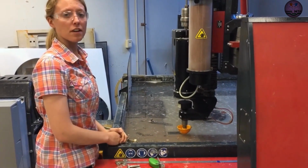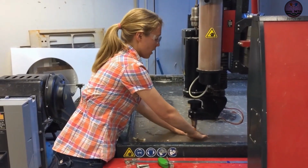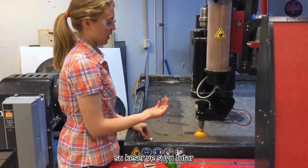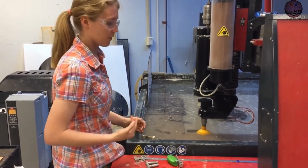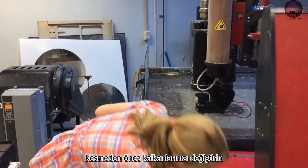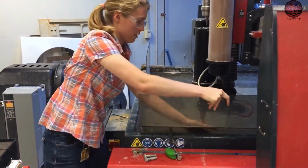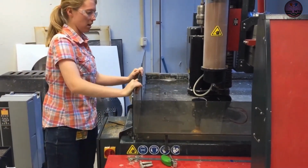When you're ready to begin your cut, flip the yellow cup down. This cup prevents any splashing that might occur while the water jet is cutting and keeps the water contained so it doesn't get all throughout the room. You'll also need to replace the shields, set them back on their ledge. And you are ready to go.